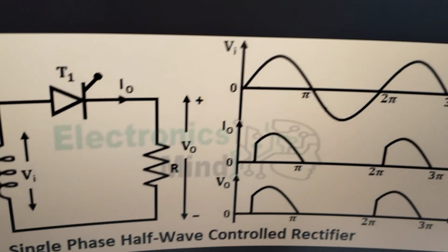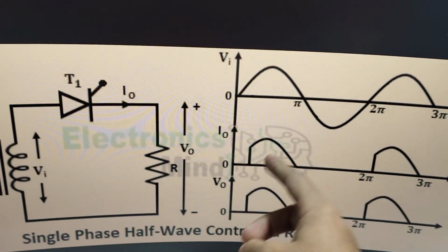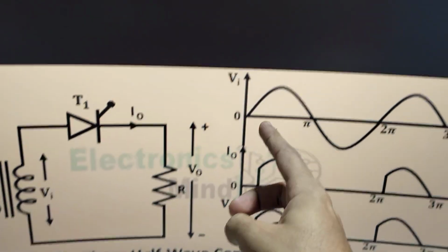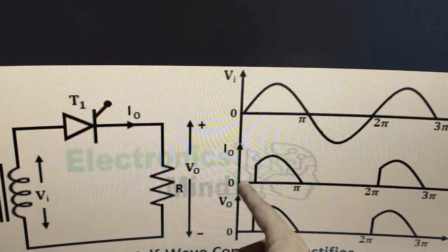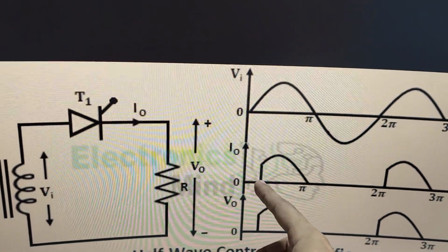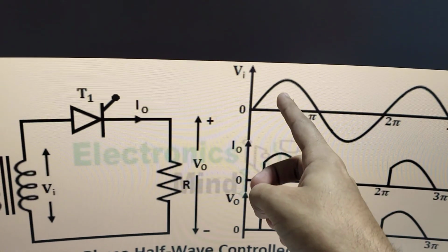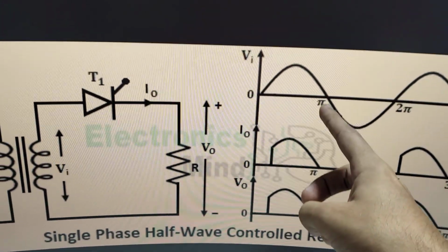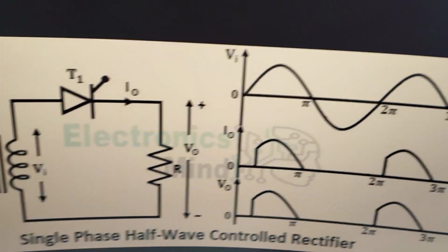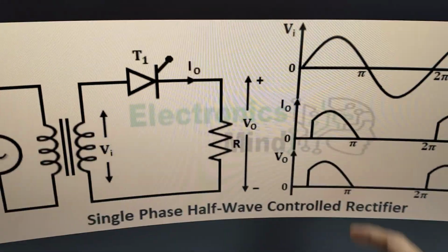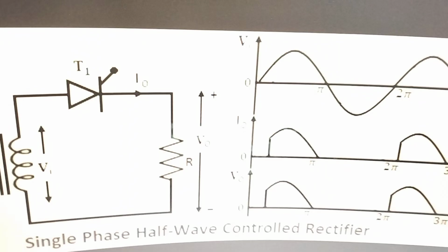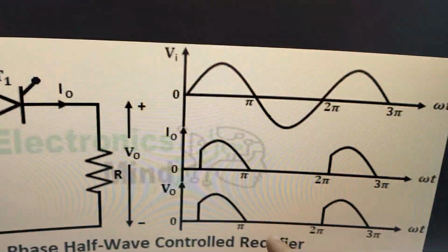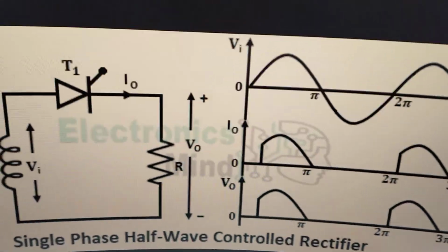A single pulse at the gate of the thyristor, and then this turns on, and it will conduct and follow your input sine till pi. You can see we gave the firing angle here. Up till then there was no output. We gave the firing angle, and it continues to pi, which is your zero crossing, where it goes into the negative half cycle. Since we are only doing the half wave here, it naturally commutates, what they call natural commutation, because the SCR turns off.